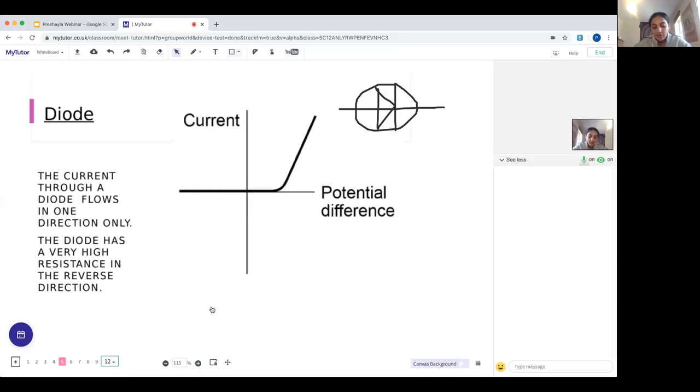So residual current breakers are the kind of safest version, and they still prevent electric shock, but they do it much quicker and much more efficiently. So it automatically breaks the circuit as soon as it detects a surge in current. But with the fuse, the wire in the fuse has to melt, and then if that does happen, you need to replace the fuse.